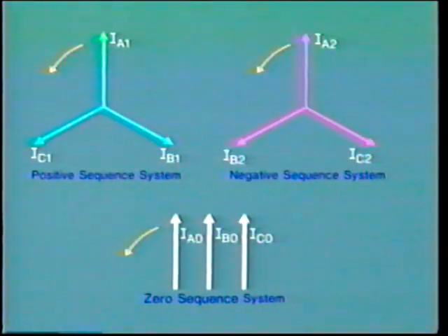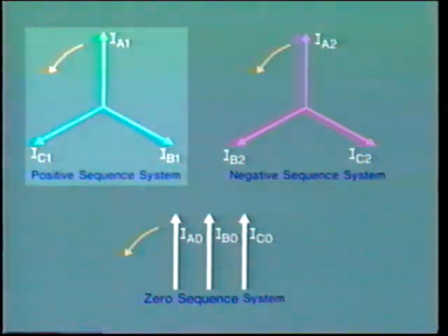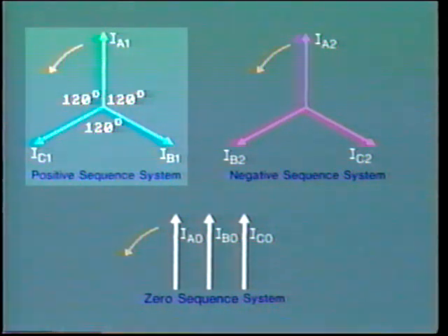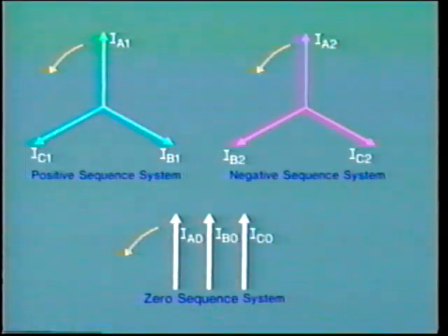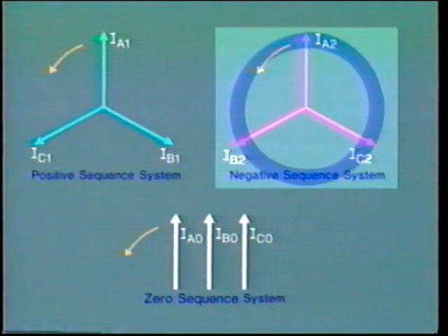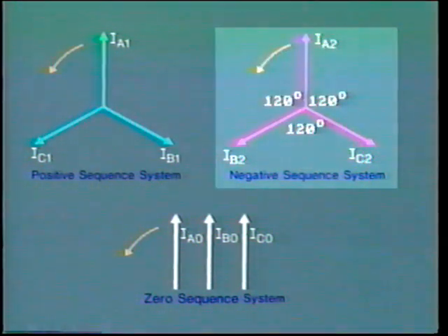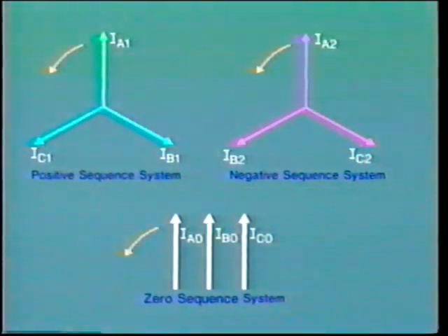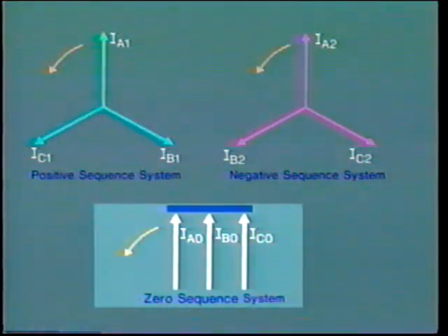The main points to remember when dealing with symmetrical components are: 1. Positive sequence components are of equal magnitude and rotate with the sequence ABC. The phase voltages are displaced equally by 120 degrees. 2. Negative sequence components rotate with the sequence ACB. As before, the magnitude in each phase is identical, and the phases are 120 degrees apart. 3. Zero sequence components are also of equal magnitude, but rotate in phase. The phasors are fixed in relation to the